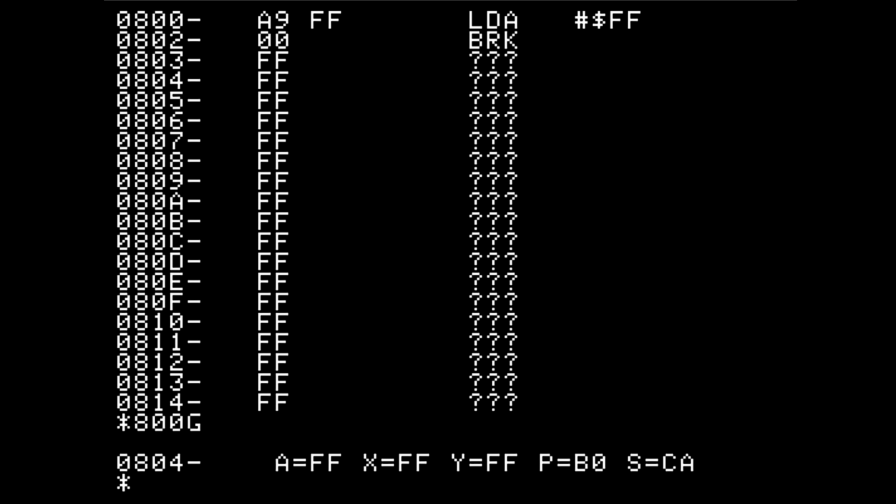Bit 6, which is the next bit to the right, is the V flag, which stands for overflow. In order to understand this, you need to understand a bit about 2's complement arithmetic. We discussed this in some detail in our arithmetic logic video. We also implemented some 2's complement circuits in our arithmetic logic lab, and we also implemented an overflow bit, as well as some of the other status bits that we're talking about today in our arithmetic lab video.